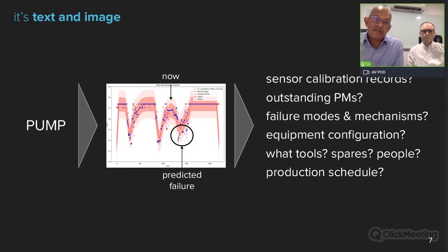Well, it's stuff like this. First thing she's going to want to know is, am I looking at an equipment failure, or is it the sensor which is failing? Do I have some outstanding preventive maintenance work orders which I pushed out because I had to go fix something else? Maybe just a simple oil change will fix everything. Not all failures are easy to diagnose.